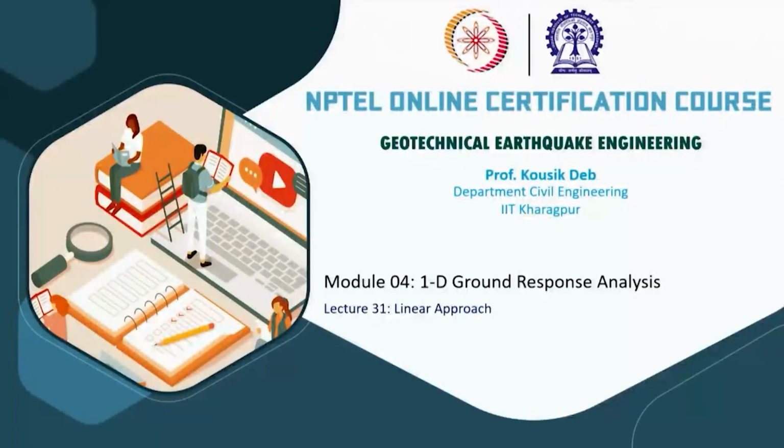And in today's lecture I will start the 1D ground response analysis. Before I start, I want to give one more piece of information: how we can establish a relationship between the damping ratio and the secant modulus, because in the equivalent linear approach we discussed how to determine the damping ratio and how to determine the shear modulus.